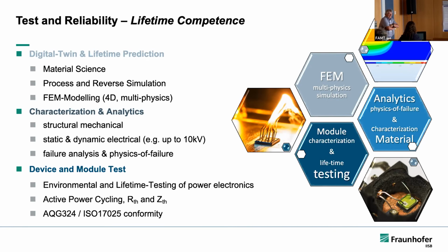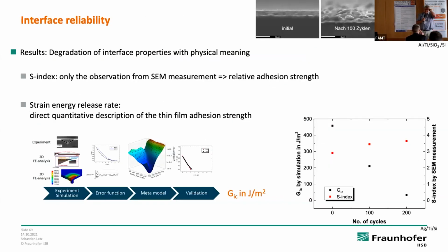Thank you very much. Maybe just a brief question. Could you comment on the resolution of this lock-in thermography? This looks quite interesting. In terms of temperature or spatial resolution, basically it's a microscope, so a factor of 60, what you expect on a microscope. The problem with the resolution is not the optical, it's the blurring. So the temperature propagation. Temperature will not be localized.